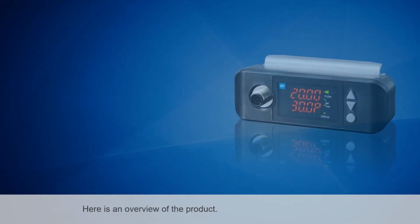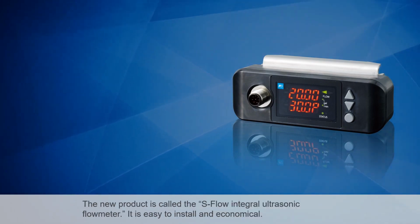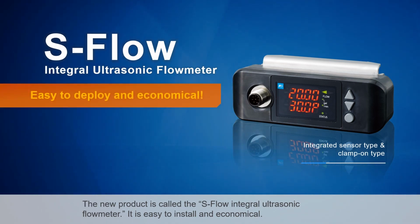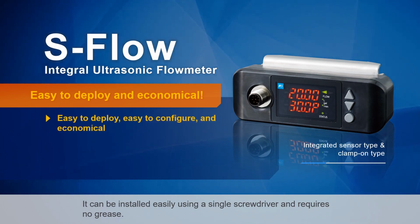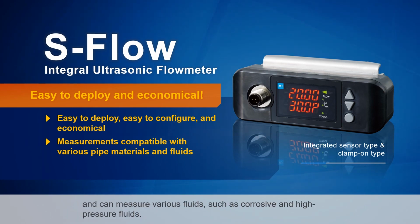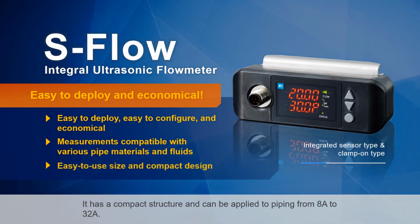Here is an overview of the product. The new product is called the S-Flow Integral Ultrasonic Flow Meter. It is easy to install and economical. It can be installed easily using a single screwdriver and requires no grease. It can be used with a wide variety of pipe materials, including copper and PVC pipes, and can measure various fluids, such as corrosive and high-pressure fluids. It has a compact structure and can be applied to piping from 8A to 32A.